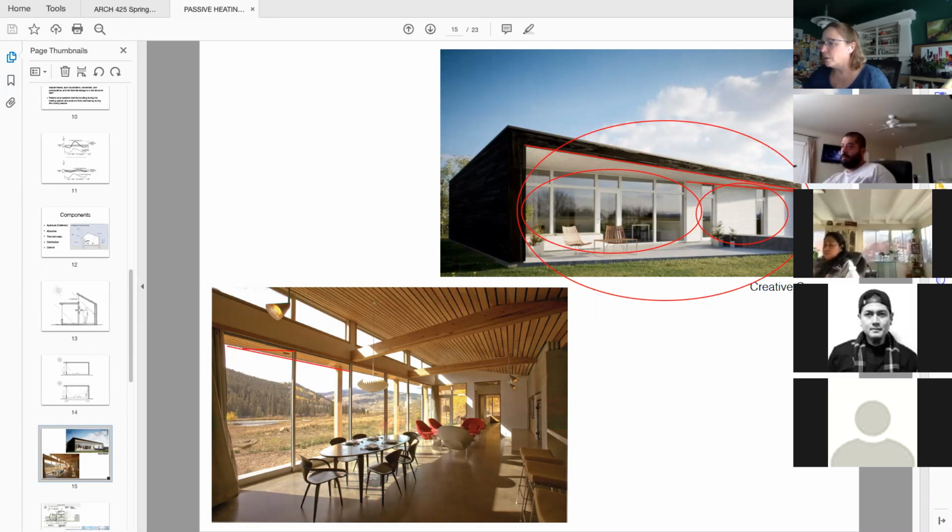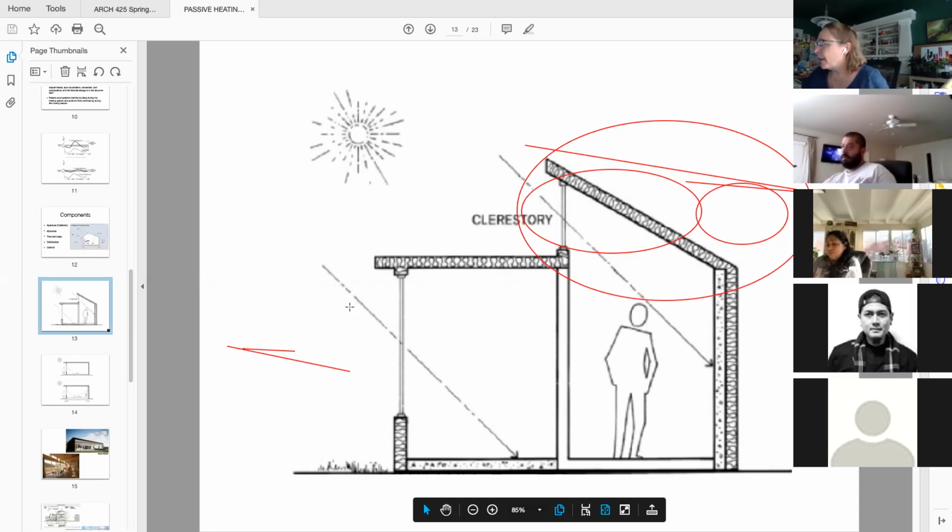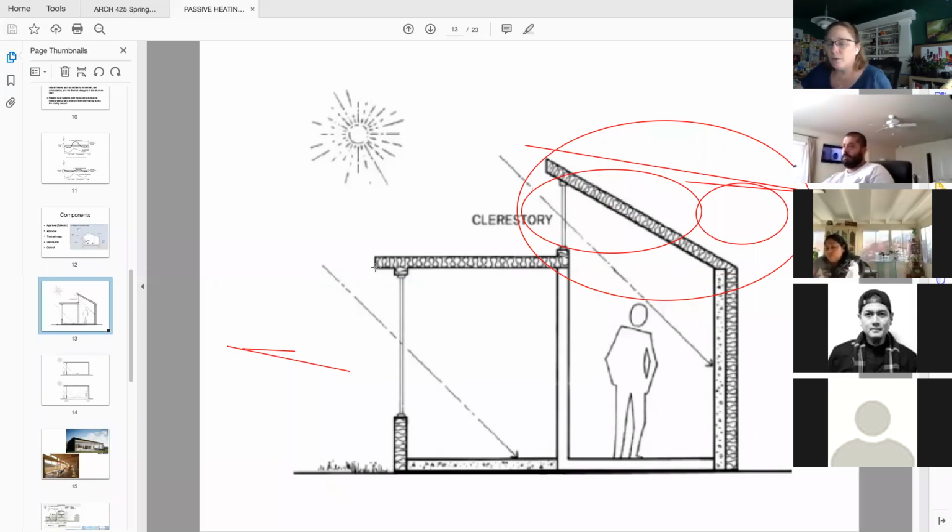And it's a pretty straightforward calculation in your building section. You draw your building section, you draw your overhang, you look up on your solar chart or use your computer program to find out what that angle is at that time of day. Good things to look at would be, say, June 21st. Okay, I know I want maximum shading at June 21st, but if a little bit more sun starts coming in before and after that, that would be the maximum length that you want.